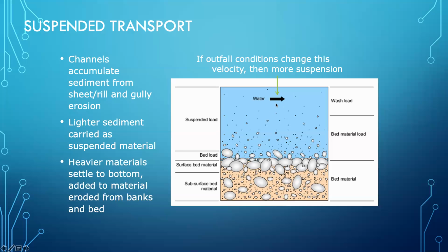When the water has relatively high velocity, there's quite a bit of shear force at the bed, and that suspends or resuspends material and starts pushing it downstream. When the velocity drops to a lower level, that shear force is declined considerably, and the bed will remain stable. So in terms of outfall design consideration, keeping that in the back of our mind, velocity is going to play an important role.